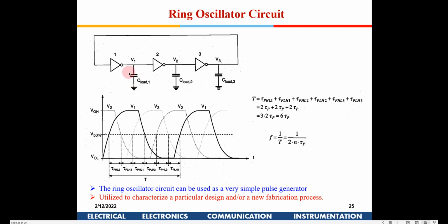How much frequency can it offer? This is dependent on I on and the capacitance, the I on divided by CG ratio. When I am moving from one technology to another, if I simply increase I on by increasing gate capacitance, it is of no use to me. So I have to increase the I on to CG ratio.